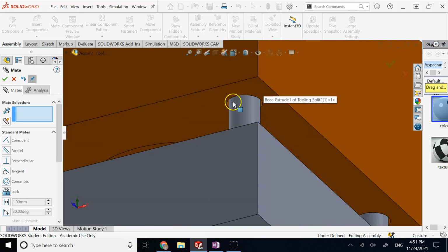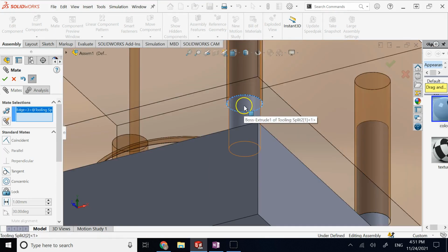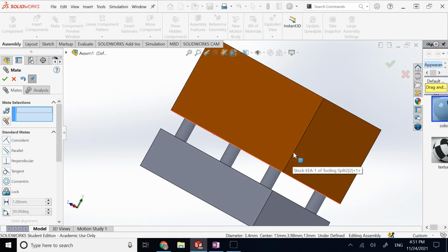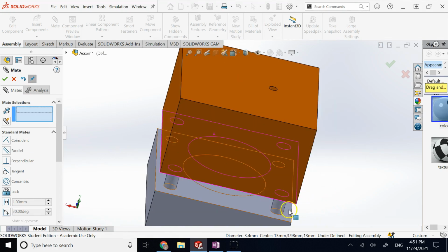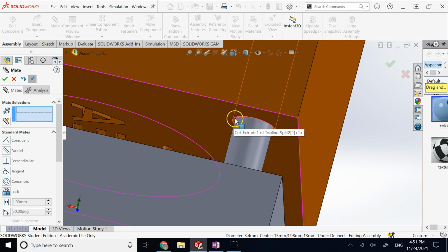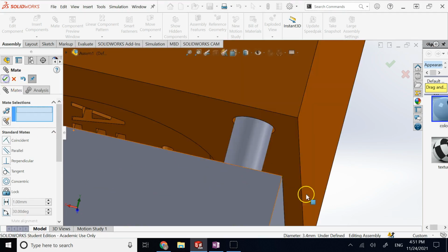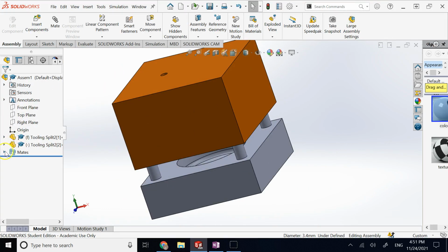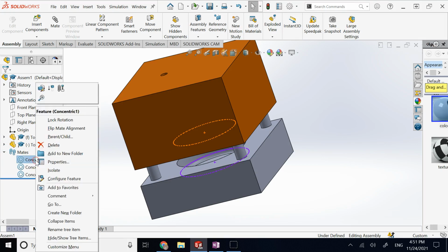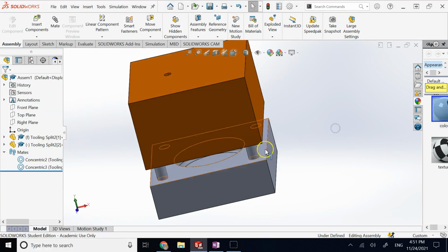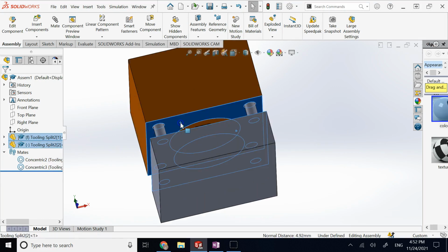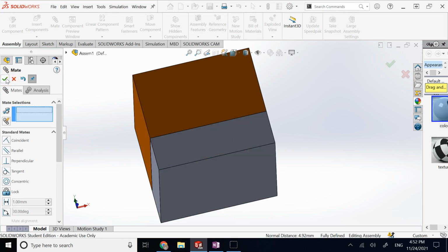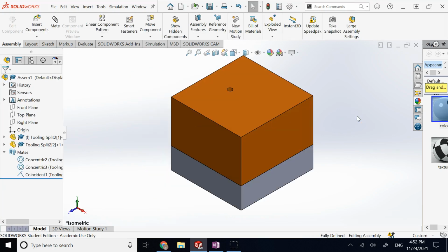And then to make sure, again, everything is in good condition, I make those two also concentric. So now it should be good to go. I assume you can add one more, although you have to make sure it's not redundant. So this is another one. If I use two of the guides, by the way that I did it, this one is really redundant. So let me get rid of that. And then you can also make these two coincident, right? Flush, like this. Sitting, and there we go.